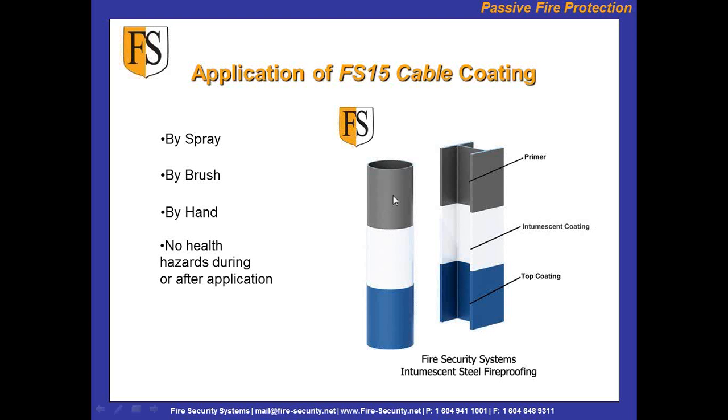So what we would require at least is a data sheet and an MSDS of the primer, so we know that there's not going to be any adhesion issues. Usually we want non-zinc primers. All of the grey and red oxide primers, which are 95% of the world primer base, are all non-zinc based. So you'll get the steel pre-primed.